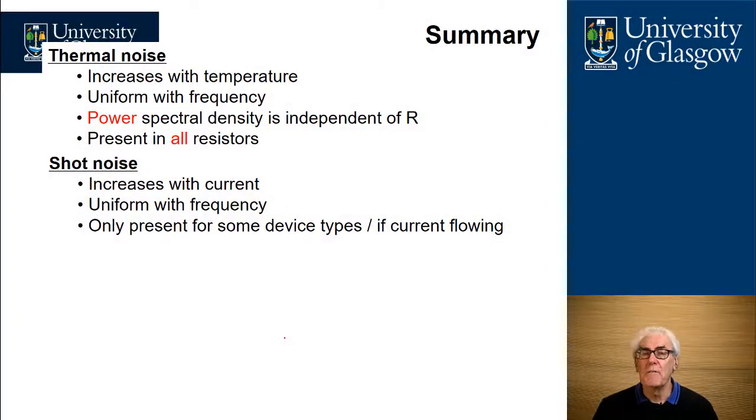So, summarizing our noise: thermal noise increases with temperature, but it is uniform over frequency, and the power spectral density of thermal noise is present in all resistors.